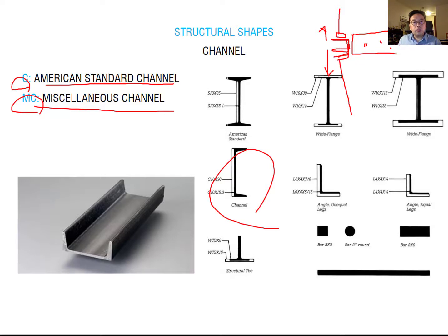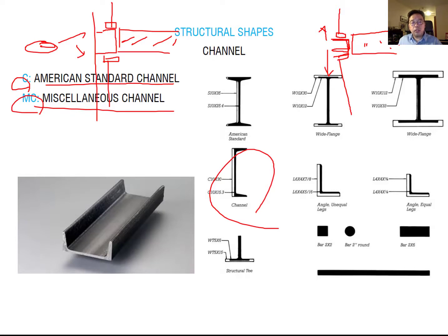Okay, so I will redraw this. This is your concrete slab. And then you just design the channel. You also cover your concrete edge, and then you just add the window. So when you see it from the outside, you can see this continuous profile. You don't see the concrete edge from the outside. So it means you can design a much cleaner looking facade. Okay.